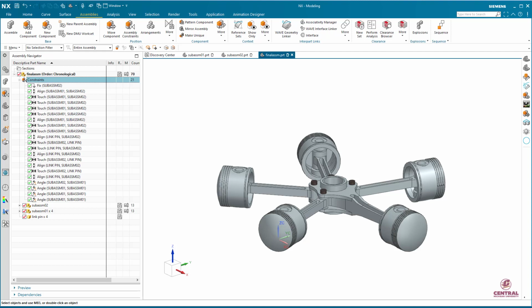So it's gonna be much cleaner. For now, I wanna see it, because as we learned, if constraints conflict with each other, you can find out very easily because the color will change automatically. And also, same way as you're seeing in the subassembly, subassembly 2 being used only once, subassembly 1 used 4 times, it's been suppressed like that, right?